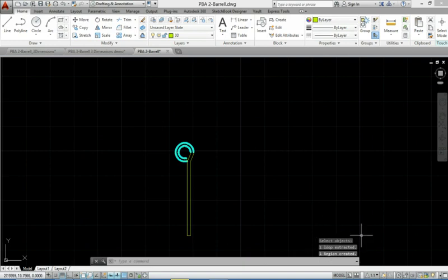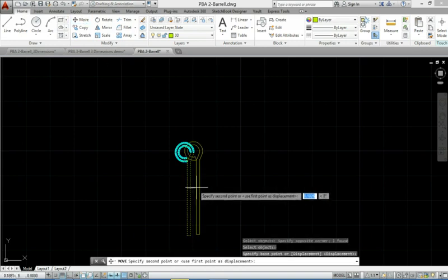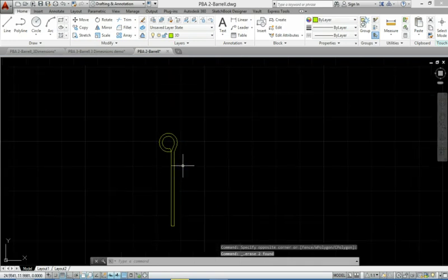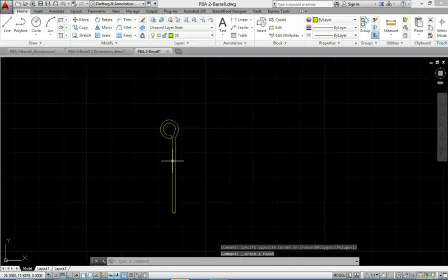You'll get a message on the bottom right here that says one loop extracted, one region created. If yours says 0, 0, that means you do have a mistake, so you need to go find out what that is. Now I happen to have 2 extra blue arcs, but they're not part of the region, as you can see when I move this apart. So these are not needed. You probably don't have that situation. I did because I made this part more than once.